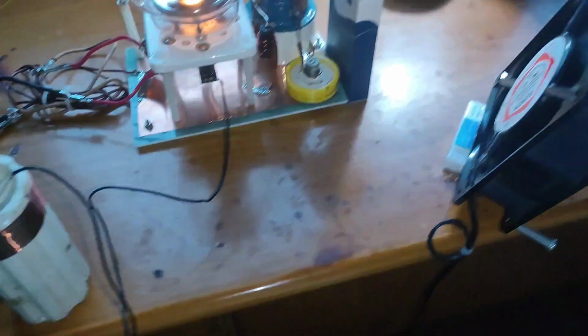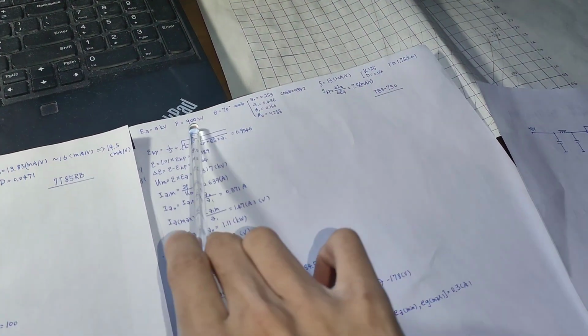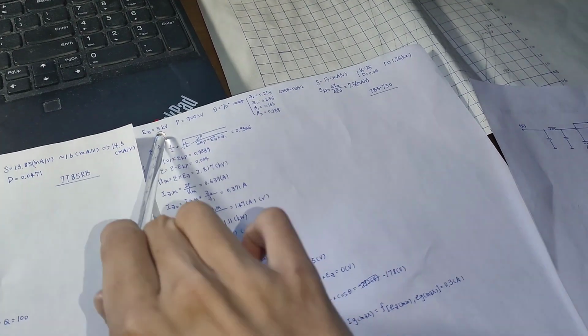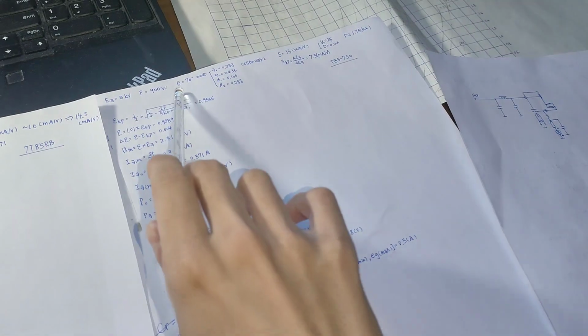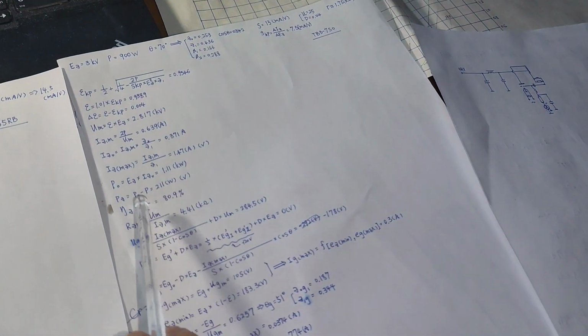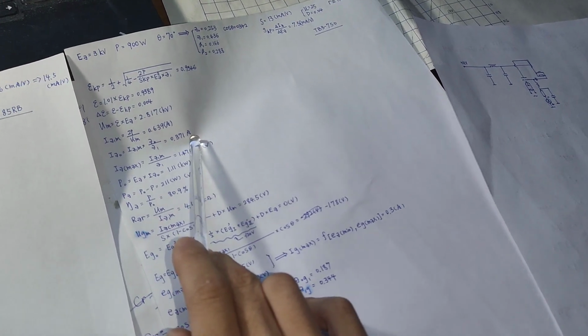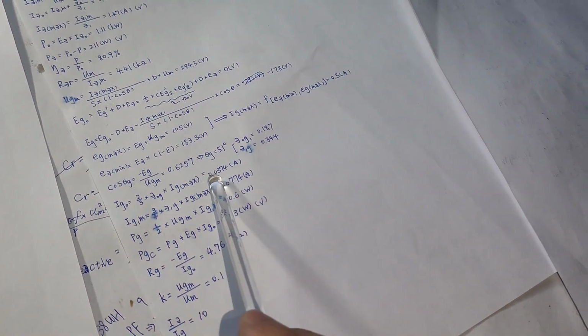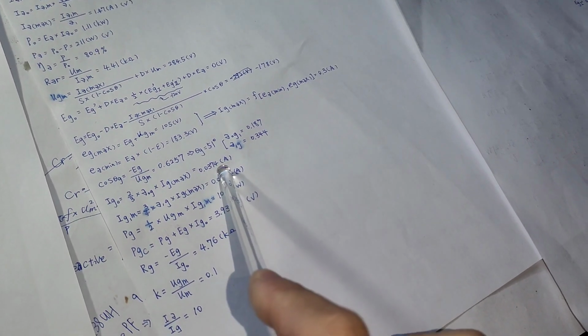And as you might remember here, our design power output is 900 watts, and the design voltage is 3 kilovolts, while this power will be achieved at around 0.37 amps. And the grid current, as we just talked about, is around 37 milliamps.